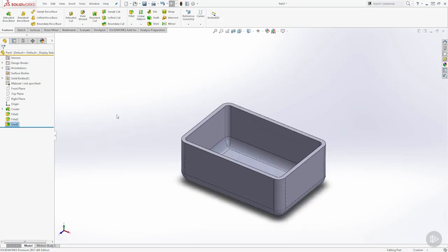And what we want to do is figure out the volume of it. There are several different ways that you can do this. You can do it with surfaces, which is usually the go-to method if you've been around SolidWorks for quite a while, since at least before 2013. And there are other methods that you can do, but this is where making the top plane the top of my part is going to make sense.